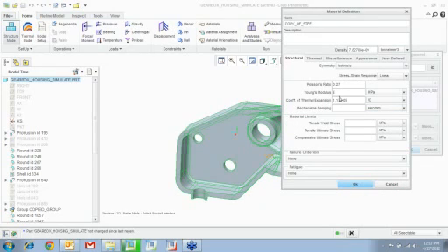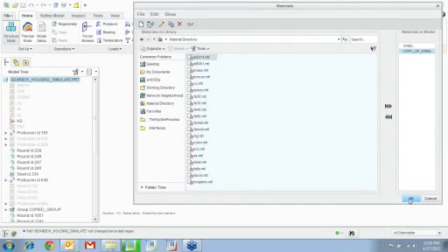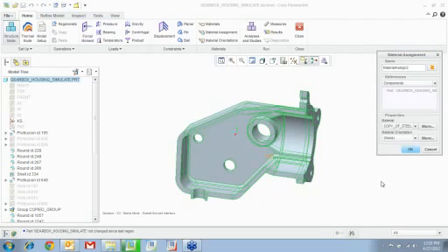Now, what is the advantage of this E? Now, let's say, for example, you're using stainless steel, and then you want to go ahead and say, hey, what happens if I want to use a different grade of steel? So you can vary the Young's modulus, and you can plot stress strain curves, or say, for example, your displacement to your Young's modulus curve. You can see which type of steel gives you the best possible result. Okay, you can also do that.